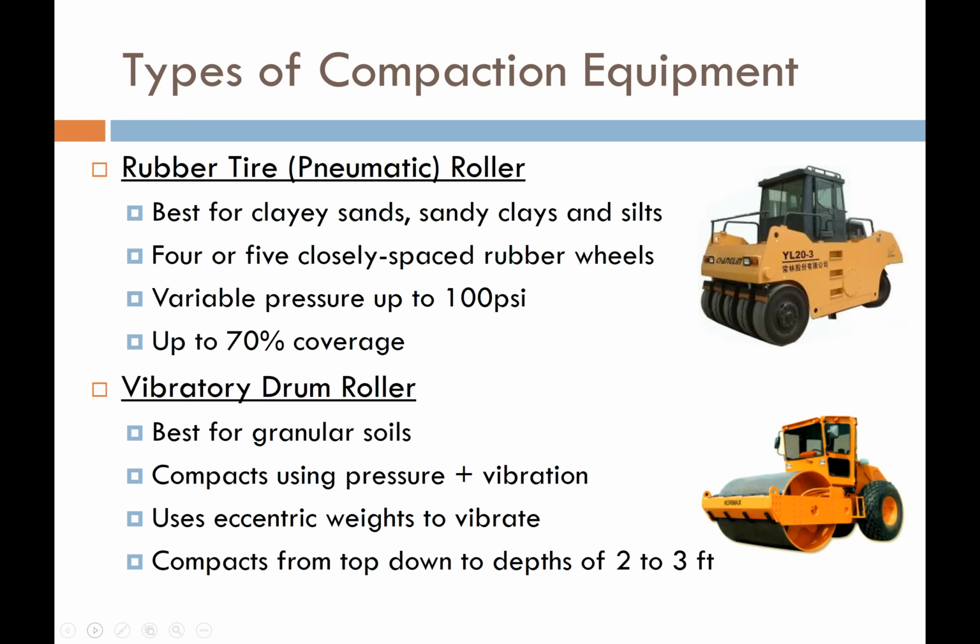to vibratory drum rollers, because they vibrate up and down. And so these are really good for granular or coarse-grained soils, but not so good for fine-grained soils. This vibratory action can actually over-compact fine-grained soils and lead to pumping.